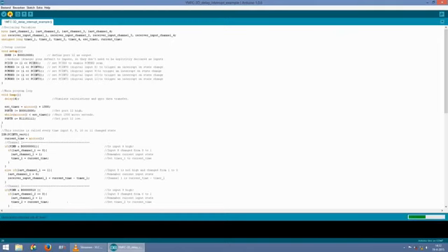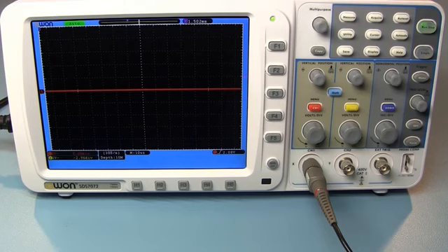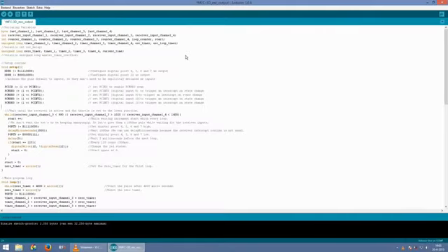And when it does, the output is set low. Despite the time it takes to read the microsecond function, the nasty microsecond correction and the interrupt routines that run in the background, we get a pretty decent pulse. Now the maximum jitter is approximately 20 microseconds and will do the job for our flight controller.